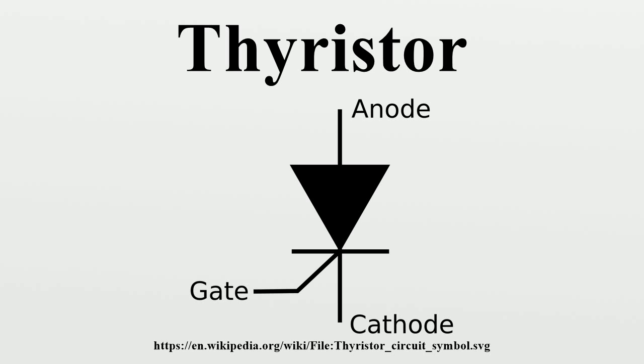Thyristors have their own particular modes of failure, including turn-on di/dt, in which the rate of rise of on-state current after triggering is higher than can be supported by the spreading speed of the active conduction area. Forced commutation, in which the transient peak reverse recovery current causes such a high voltage drop in the subcathode region that it exceeds the reverse breakdown voltage of the gate cathode diode junction. Switch on dV/dt. The thyristor can be spuriously fired without trigger from the gate if the anode to cathode voltage rise rate is too great.